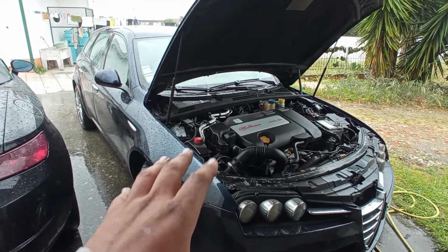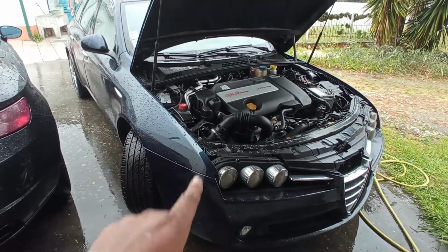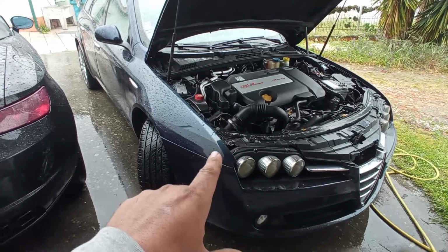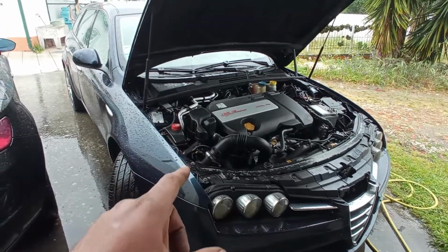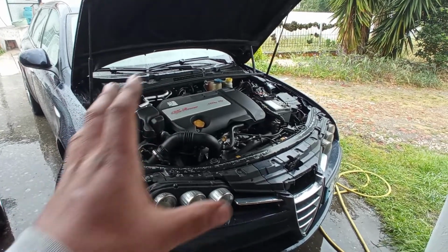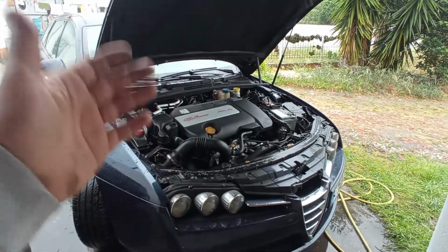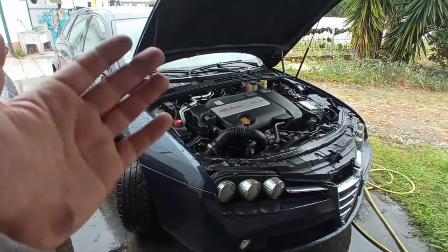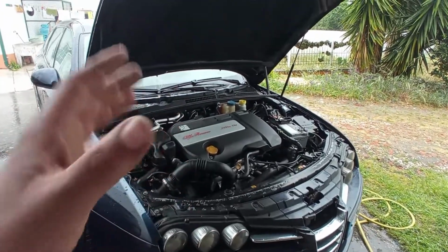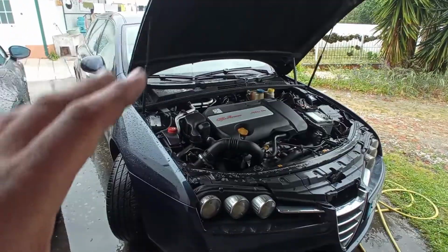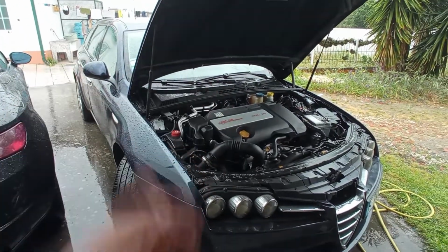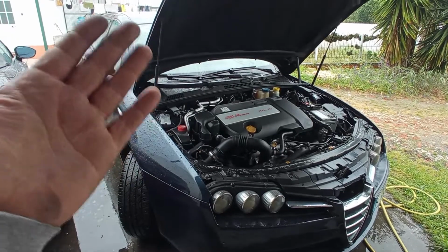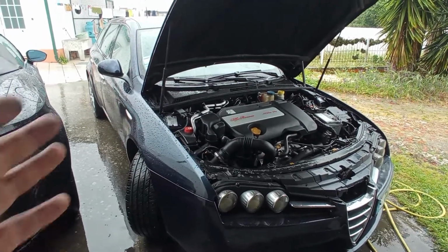My idea with this was that the issue of the air filter, as you've seen before, caused several other problems with that mass airflow meter, with the restraint of the air to the engine, caused the constant regenerations maybe, and for that they tried to mend it with a remap. The remap was very bad, and with that more and more problems appeared on the car. That's why the car was for sale in the first place.